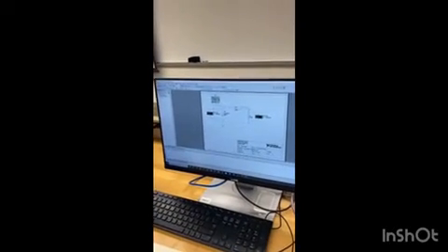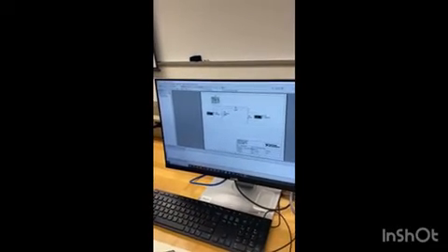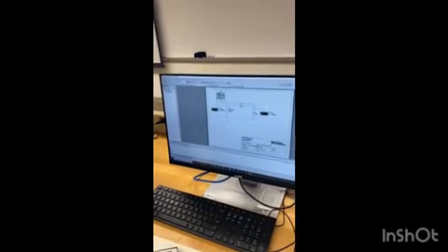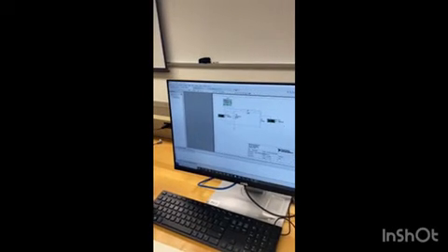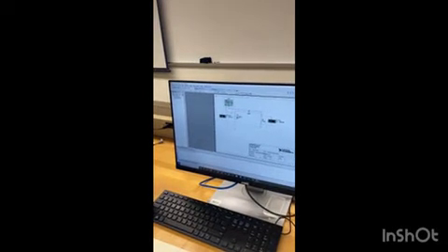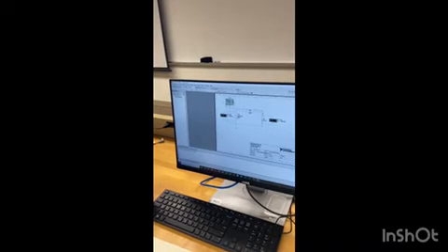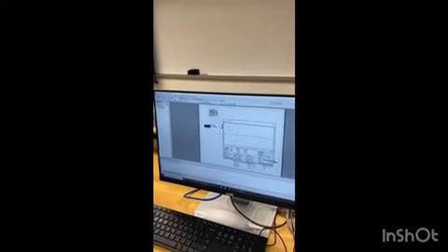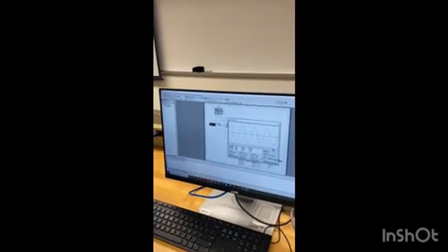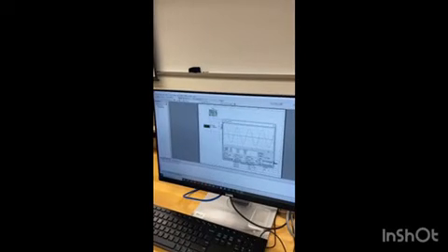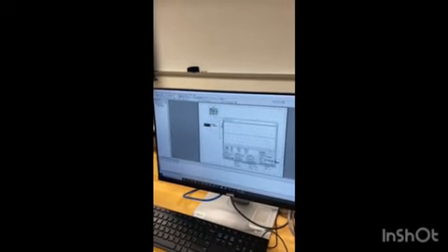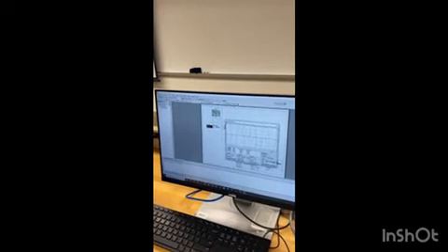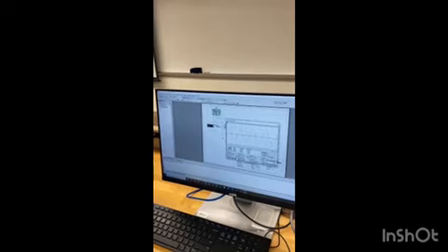And then we have a series circuit, 1.5 kilo ohms and 2.7 kilo ohms. I'm gonna show you the V peak to peak for the power source VN. I'm gonna run the circuits. Give us 2.474 VRMS. On the oscilloscope channel, I'm gonna stop oscilloscope here. Gonna go take a good image. Take channel B off. Take channel A. I'm gonna change the frequency here.